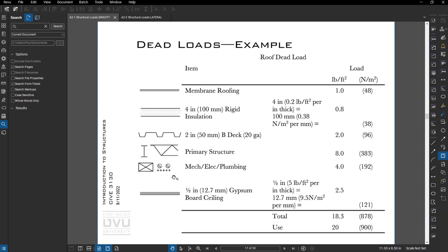Don't get too wrapped around the wheel about accounting for every light. Generally what we do is apply 3 to 5 pounds a square foot to cover those things. In industrial structures, we'll look at it closer because we may have really substantial pipe or duct loads or equipment loads. So we basically come in, I like to list what it is, pounds per foot.